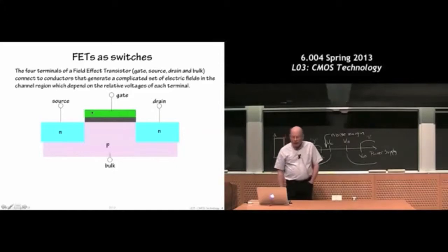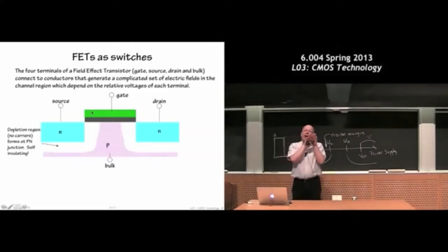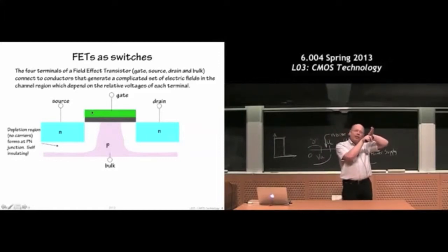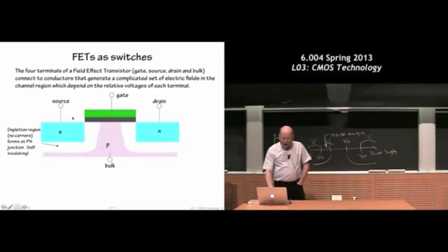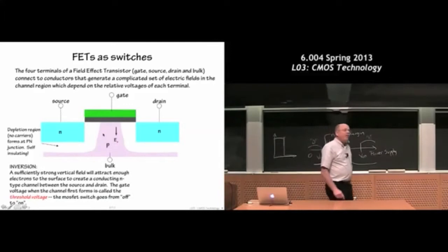So initially what happens is when we put this together, see what happened there? See how some of the pink went away? If you put these P and N-type devices together, initially what happens is that the mobile carriers move around. And they actually move out of it right at the junction between the P and the N, the P-N junction. What happens is the mobile carriers, what's called the depletion zone, they actually move out of there. So if you were a hole, you'd wander across and mate up with an N. And if you were an extra electron in here, you'd move away from the N-type devices and come find a hole to become your mate for life. And what happens is you get this depletion region, which forms a natural insulating barrier between the N and the P. So this is a so-called PN diode.